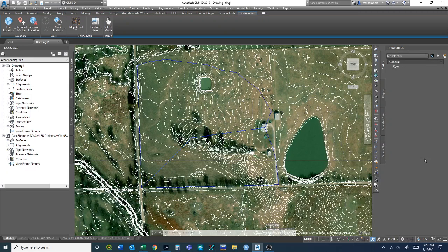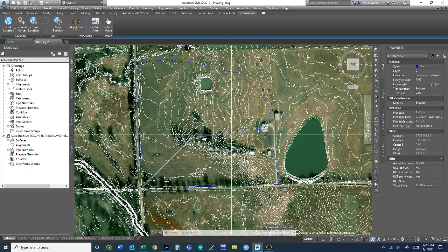This is all based on Civil 3D, and we got a high point elevation and a low point elevation, and I'll explain in a minute why that's needed. But this is what we're basing this off of, this small watershed, looking at flows to this intersection in view of trying to size a pipe to go underneath the intersection.